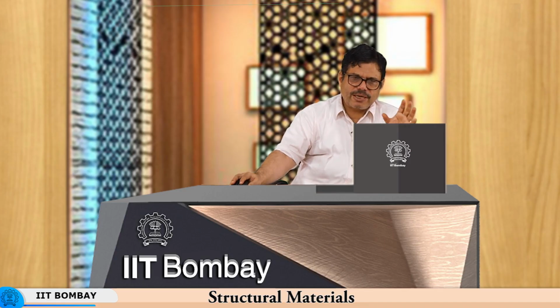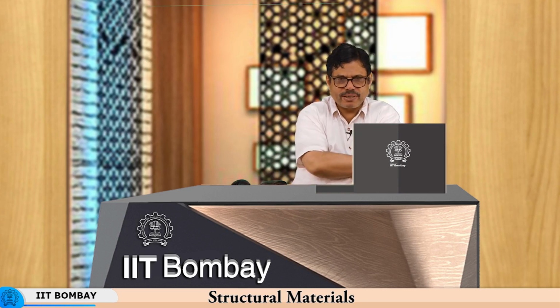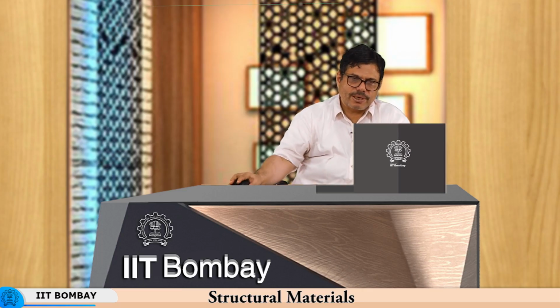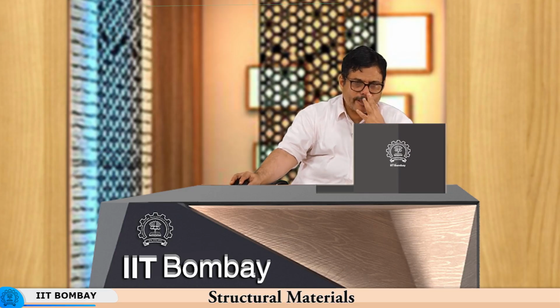So, what happens is, as you quench the article, the quenchant evaporates immediately, and the bubbles which do not leave the quenchant cover the entire surface and reduce the heat transfer rate there. Wherever bubbles are formed, the thermal conductivity of the bubbles being very low, you have a relatively low quenching rate. As a result, you create a soft spot in the region where the bubble was formed, right. So, this is one aspect.